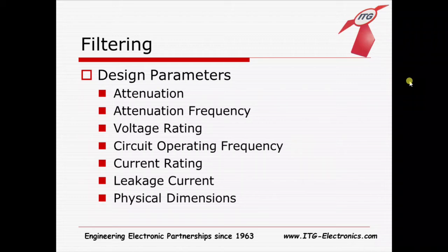circuit is being powered by, because anything coming in through the power line, you're going to want to run through this EMI filter. That's how you're going to clean the power, how you're going to get a pure signal to come through without any of this interference. So the fact that all that power has to run through there, you have to make sure that the components inside the filter are up to spec for the voltage of the circuit as well.